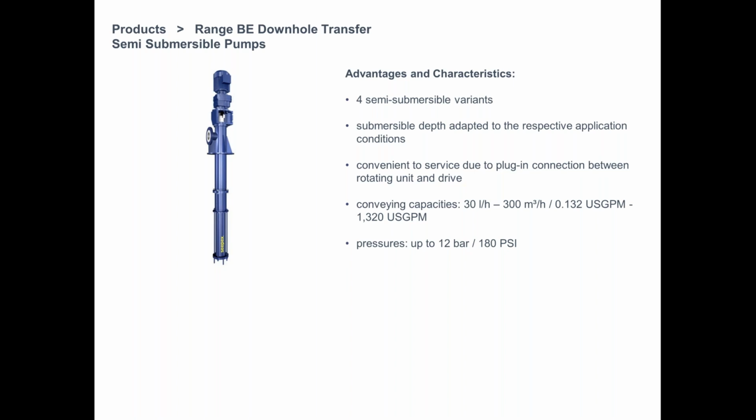To finish up, if anyone is interested in trialing a new type of dewatering or sump transfer pump, most people don't think about it, but progressive cavity pumps can be semi-submersible. So picture this style pump mounted on maybe a sump or some sort of a pit that needs to be dewatered. You can mount this pump in 4 different ways.